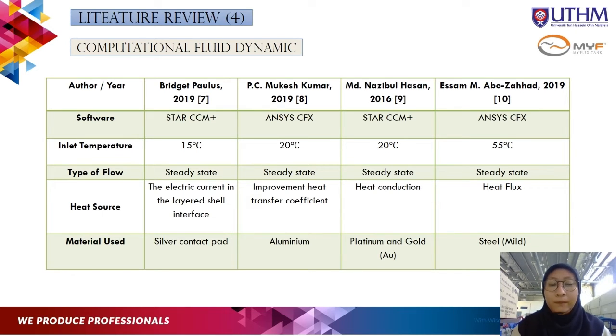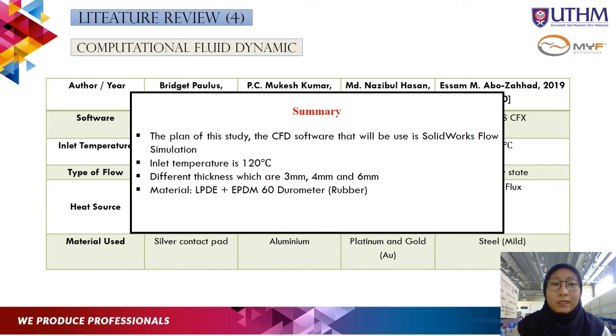For the summary of this literature review, in the plan of the study, the CFD software that we use is SolidWorks Flow Simulation. The inlet temperature is 120 degrees Celsius and the different thicknesses are 3 mm, 4 mm and 6 mm. For the material, we use LDPE with EPDM 60 durometer rubber.